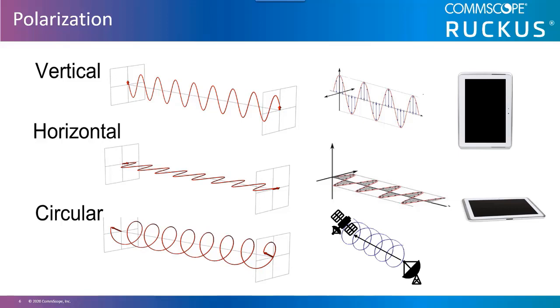In addition to placing signals into the air and receiving them, another function of an antenna is to shape the RF coverage. So changing the polarization of an antenna alters the coverage provided. A dipole antenna, or omnidirectional antenna as it's commonly referred to, has a linear polarization. When they are mounted straight up and down, they have a vertical polarization. When they are mounted on their side, as if parallel to the ground, they have a horizontal polarization.